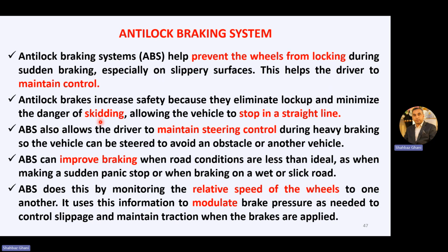So the skid distance is minimized, allowing the vehicle to stop in a straight line. ABS also allows the driver to maintain steering control during heavy braking so that the vehicle can be steered to avoid an obstacle or another vehicle.